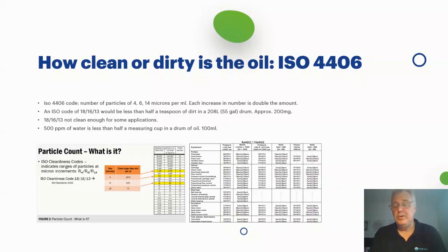Anyway, typical values of cleanliness for new oil could be around 18-16-13, 18-16-14, depending on the type of lubricant. Probably could be also 1 or 2 ranges higher, although there can also be oils which are considered the super clean oils as they go through an additional filtration process, and here they could be a couple of ISO codes lower.